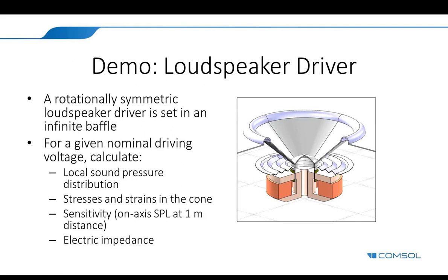In today's demo, I intend to model a loudspeaker driver, nothing less. In an experimental setup, you might mount this driver in a hole in a large reflective surface. In the model, we can make that an infinitely large plane, also known as an infinite baffle. To make the model a bit more manageable, we'll consider a rotationally symmetric driver, meaning we can model it in an axisymmetric 2D geometry. So if you look at the driver in the illustration here, this is exactly the geometry that we'll model, but we need only use its cross-section in the RZ plane.